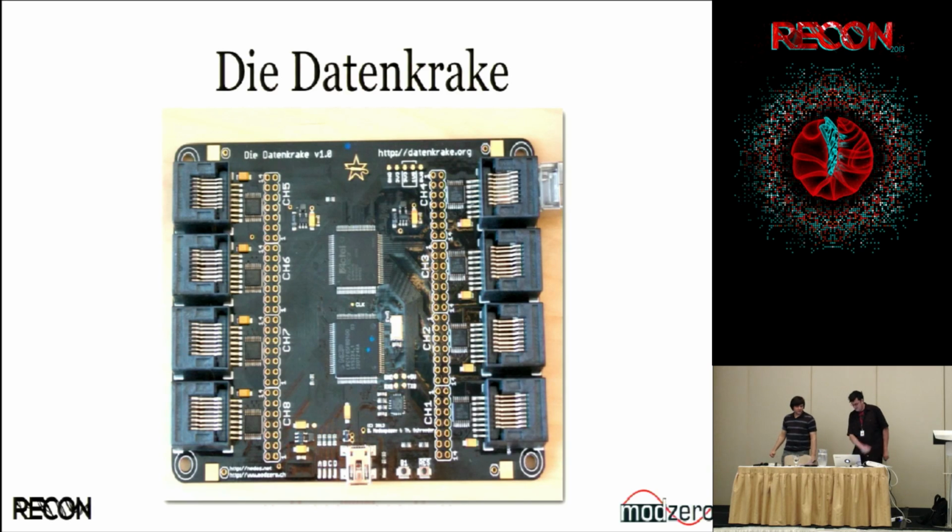Next. Good. So here we can see very quickly the ARM. Above it is the FPGA. Now we should see the USB. So here's the USB, and you see the USB comes in through the bottom. We have a newer generation FTDI. It's an FT230X, which is basically, as far as I know, the 45 nanometer silicon that FTDI uses. So for you software guys, that means it's just newer and cheaper.